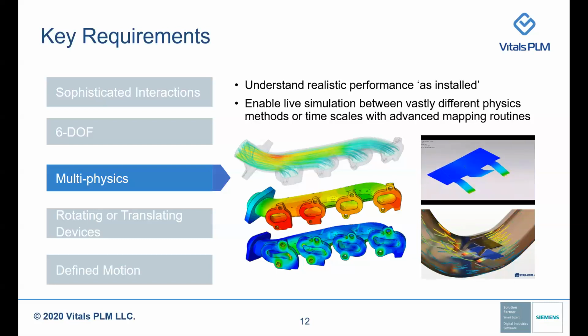The modeling approach must have the ability to accommodate these changes on the fluid side. When the structural component deforms, that should be reflected in the mesh deformation on the fluid side. So this is a key requirement in similar examples.